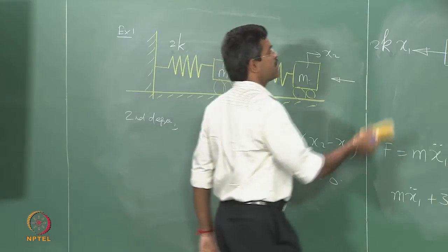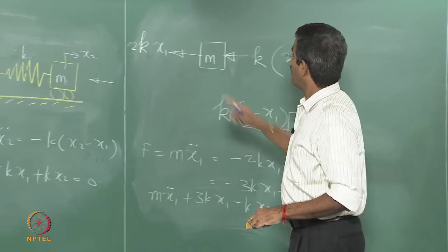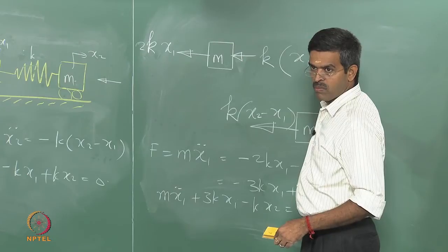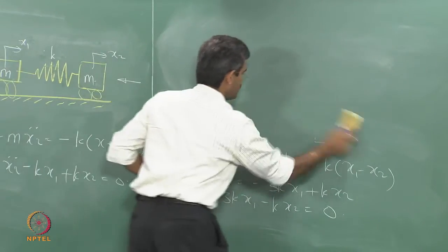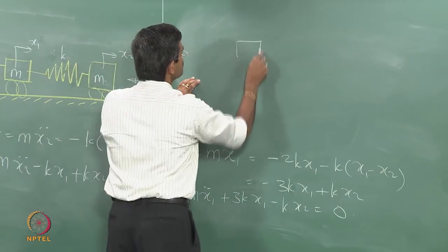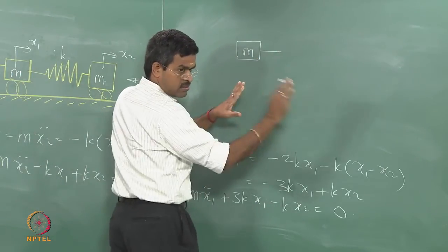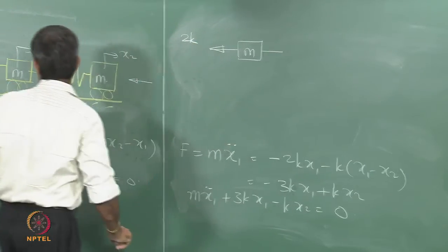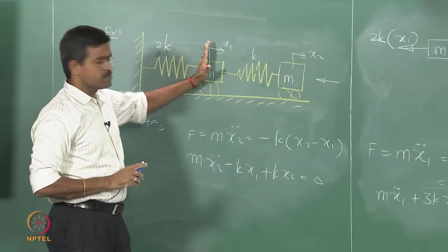I can now write in the matrix form both the equations. Now, I want to ask you a question, is there anybody who is not able to understand how I am marking these arrow directions, how I am writing these values? We can repeat it very quickly again. I will write only the figure. I have a mass which is m indicated here. The mass is going to move to the right, but the spring will not allow the mass to move. Therefore, it is the force which is spring constant multiplied by only x1, that is the displacement.